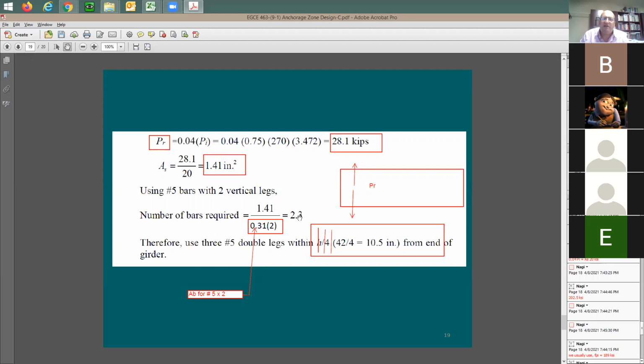And how much is the cost of putting, let's say, number 5 as a tie? You're going to see it's going to be very small. I'll place it maybe at 4 inches, and maybe a few of them is going to be okay, as long as you cover the 3 ties needed. So all I need here is only 3 ties, but I'm going to provide more, certainly.